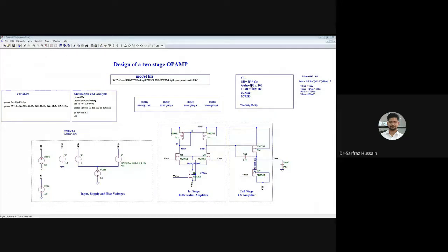So we have the gain and the unity gain bandwidth. The gain of this differential amplifier is 100, and the other 100 is for the second stage. Now we will multiply these two, 100 multiplied by 10 megahertz, the gain and the bandwidth, and this is equal to what?